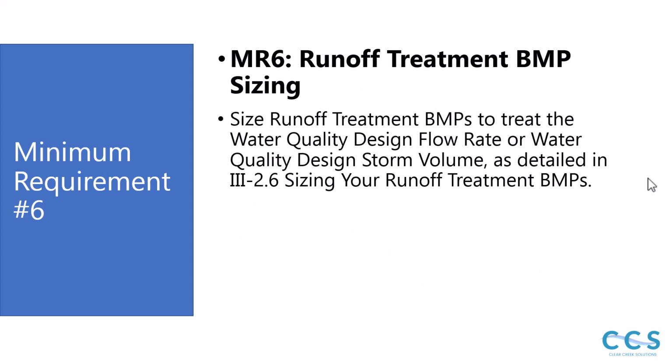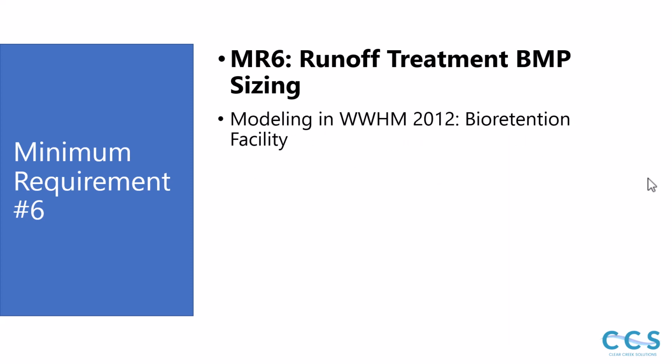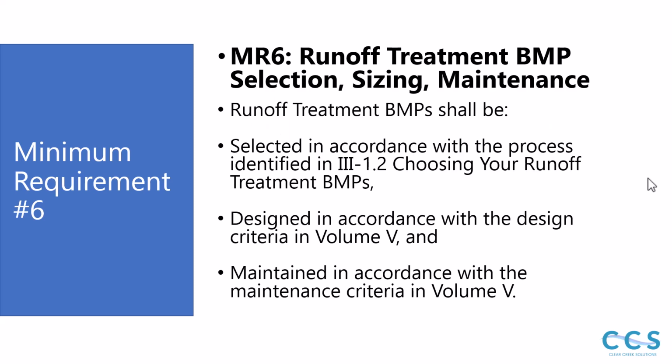So runoff treatment sizing: size runoff treatment BMPs to treat the water quality design flow rate or water quality design storm volume as detailed in 3-26, sizing your runoff treatment BMPs. We can use WWHM 2012 for this, and we're going to do this at the end. We're actually going to do a little bit of modeling there. We also have a free guide on how to model bioretention facilities in 5 easy steps. You can find that guide in the description box if you want to learn how to do that in WWHM 2012, which is a free software that can be downloaded from our website and can be used to meet minimum requirement number 6 for runoff treatment BMP sizing.